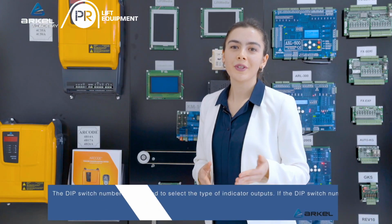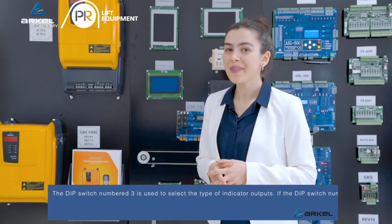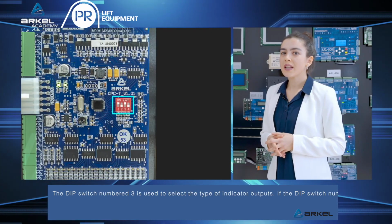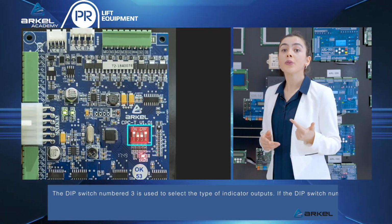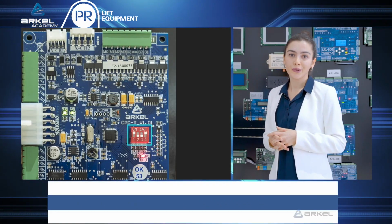The dip switch numbered 3 is used to select the type of indicator outputs. If the dip switch numbered 3 is set to on, the output is adjusted for grey code. If it is set to off, the output is adjusted for binary code.